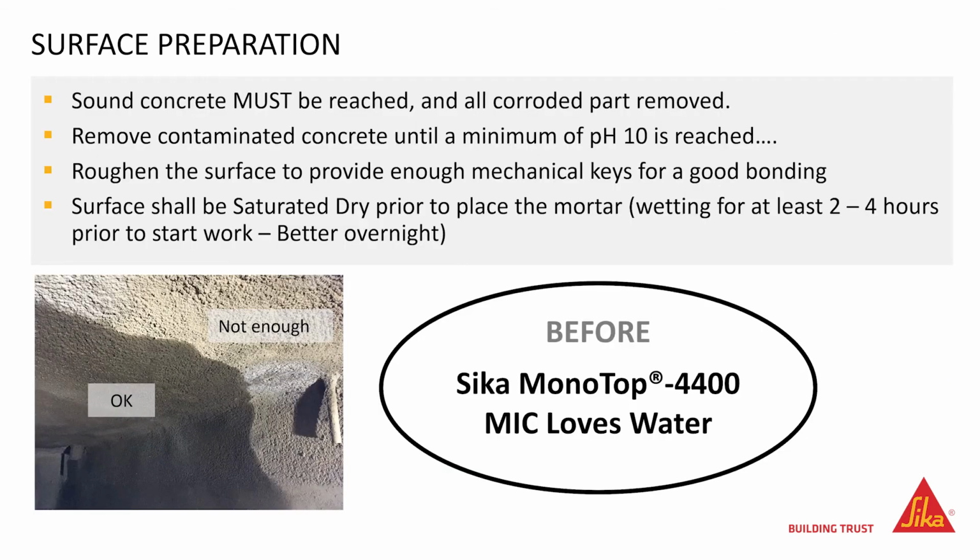This slide shows the different steps prior to applying the mortar. Sound concrete must be reached and all corroded parts removed. Remove contaminated concrete until a minimum pH 10 is reached. Roughen the surface to provide enough mechanical key for good bonding.